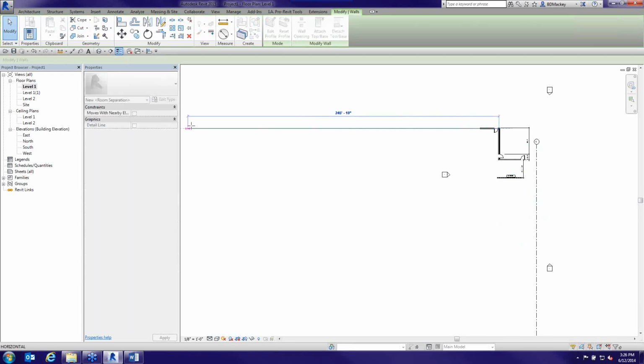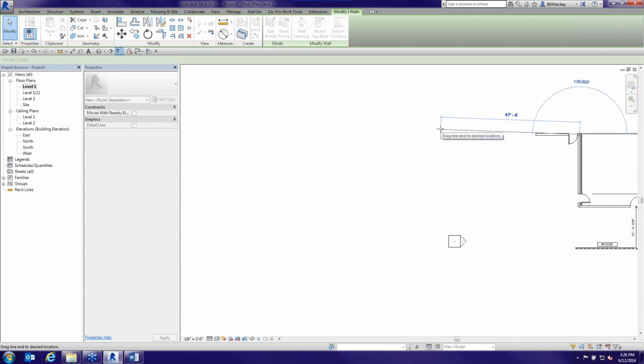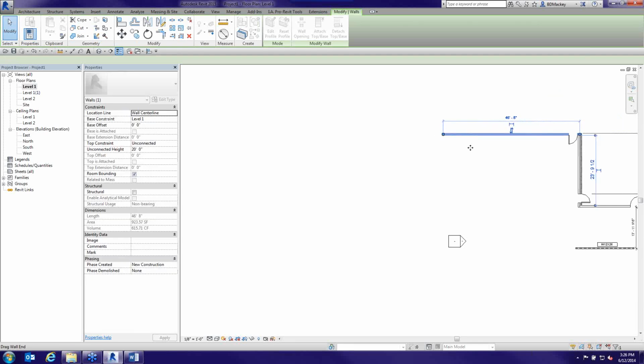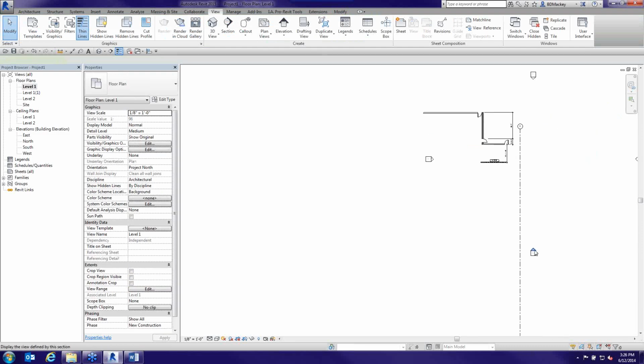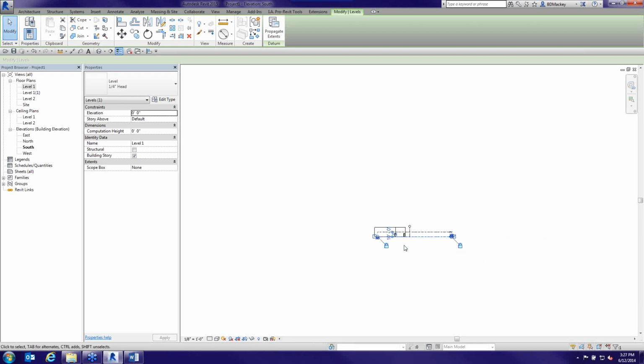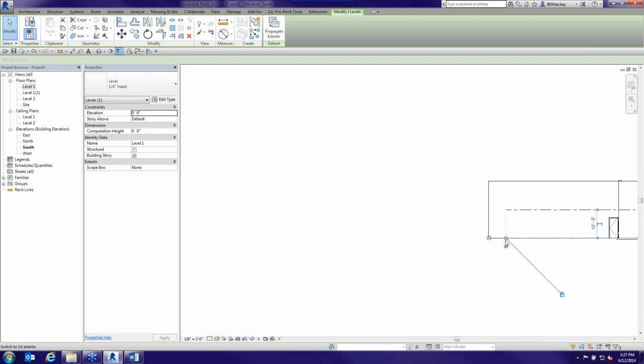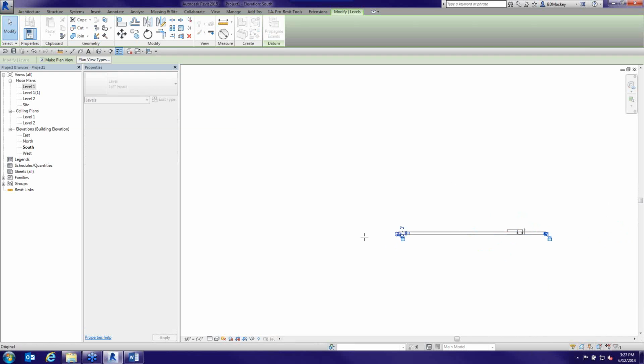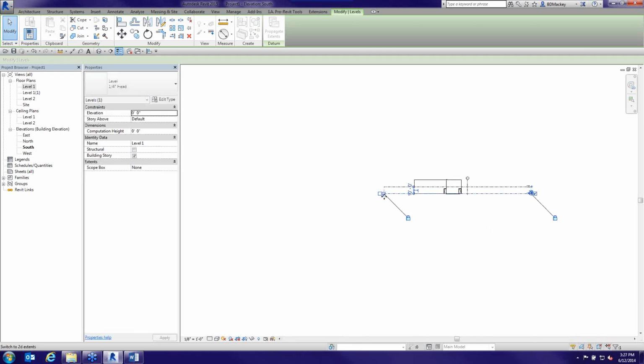It works with walls. So now I'm moving the wall up, down, left, right, and I can even release my hand to go right to type in snap center or whatever. So just drag those grips off the screen. I think the big one on this is when you get into levels. So many times I see people having to drag their levels. They're like, oh, this has got to go way over there, so let me zoom out. Oh, crap, no, I can't get the grip. Let me zoom in, then zoom out, do the claw, move it over. Screw all that. Drag it off the screen, pan, zoom, do whatever you want to do, and then click to place it where you need to place it.